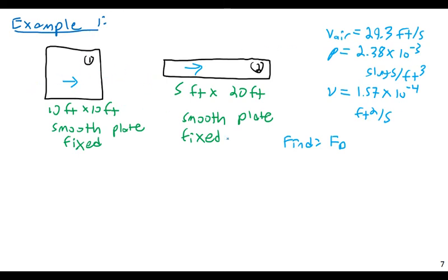Notice, what didn't I give you? I didn't give you the thickness of the plate. Since we see that, we know the thickness can't be important. For objects that are plates, there would be a small amount of drag on the edge surface, but the frictional drag, the drag from the broad flat surface, is what's going to dominate.